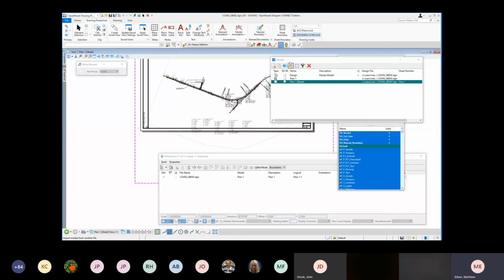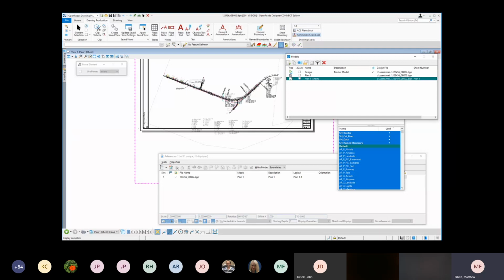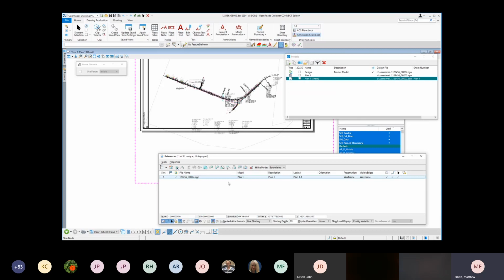You'll see that there still is the same curve data here on the plan view. And that's because the drawing model itself, the live nesting, has no real impact on it because it's a direct reference to the sheet. So we can kind of look at that better as if I turn live nesting off from my drawing model, you'll see that all of the plan information goes away.